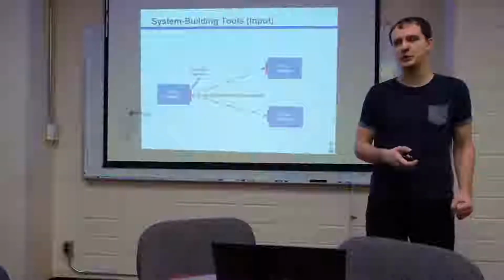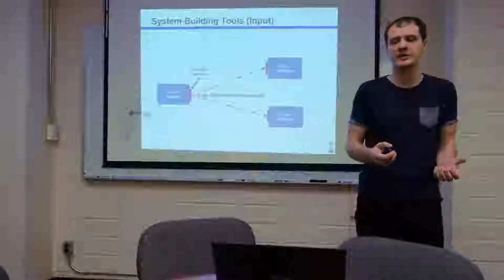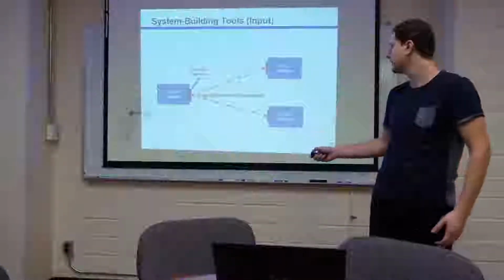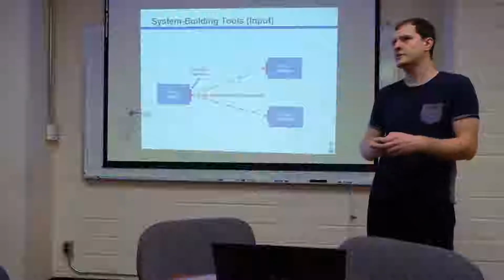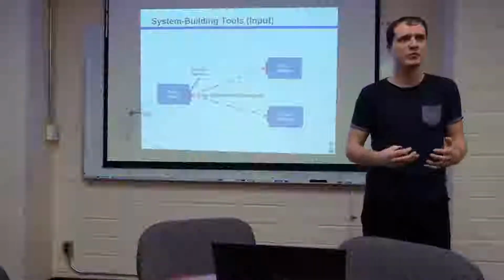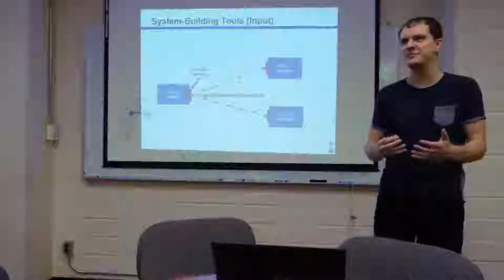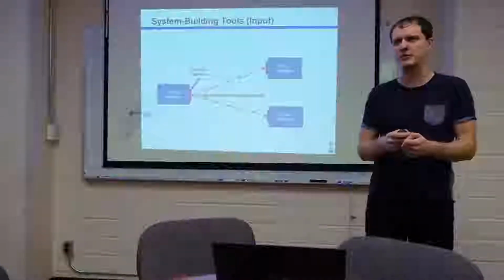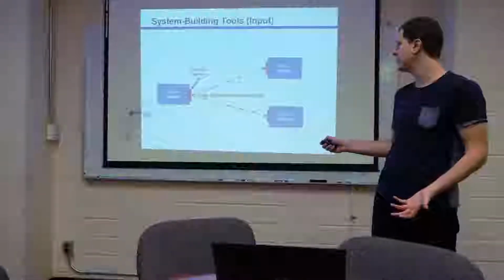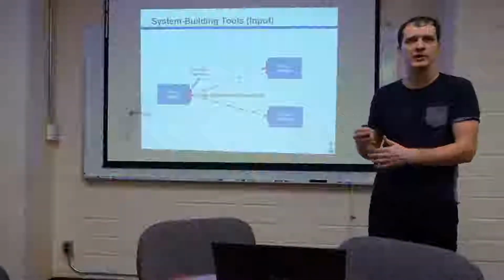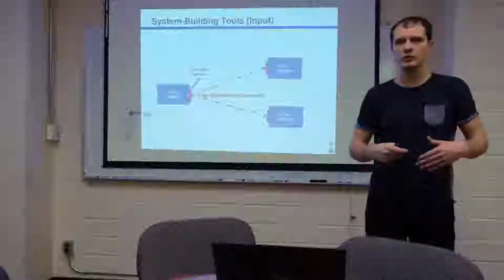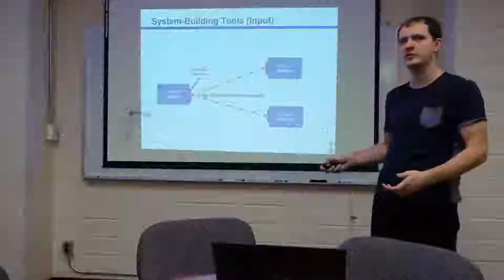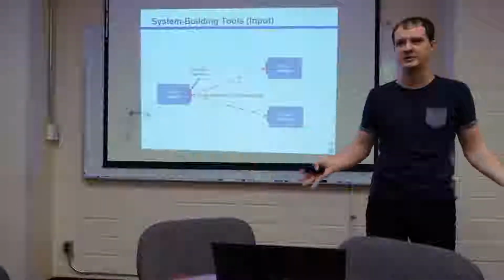The user then defines one or more logical desired links between these interfaces, and tells the tool I want these interfaces to communicate. And these represent fatter, richer connections, with more semantic meaning than just raw wires. And nominally they're directional, but they could essentially do bidirectional data transfer. So if you have a master and slave arrangement in a SoC, when you do a read, that involves both a request and a reply. So there's a lot going on in these logical links. You're asking for a lot to be done. This is the higher level aspect of these tools.